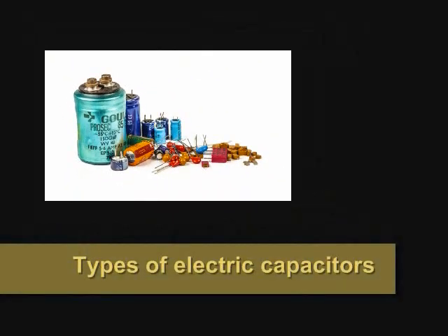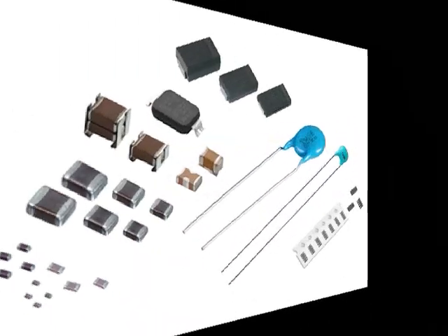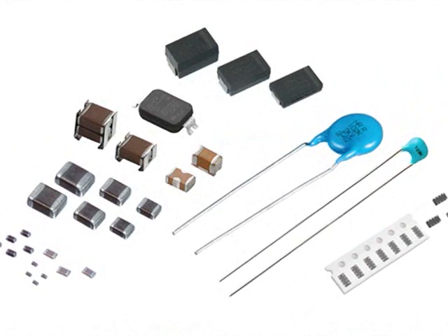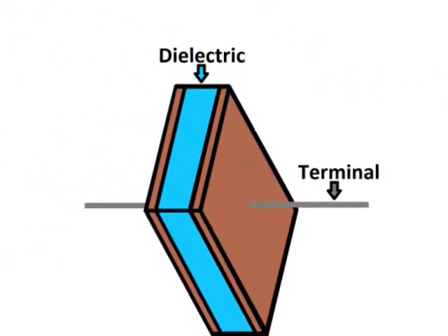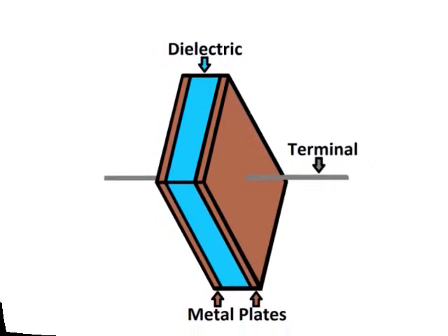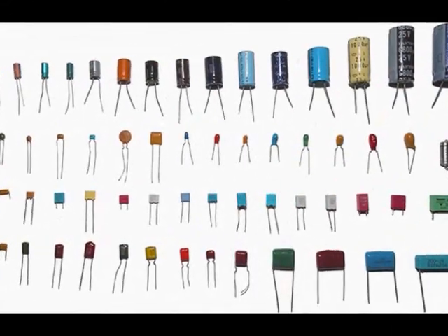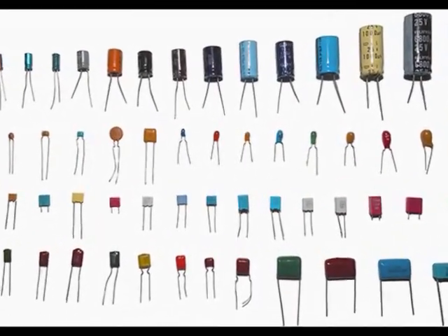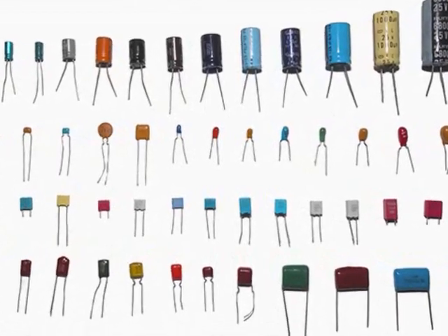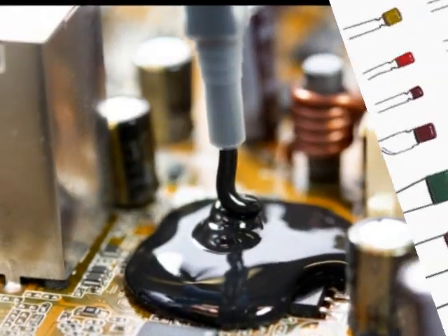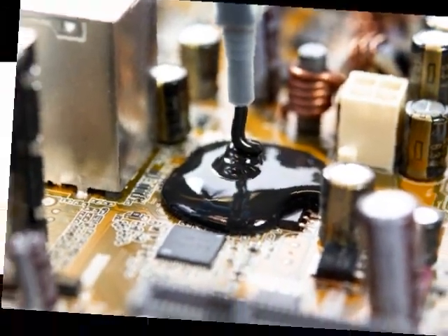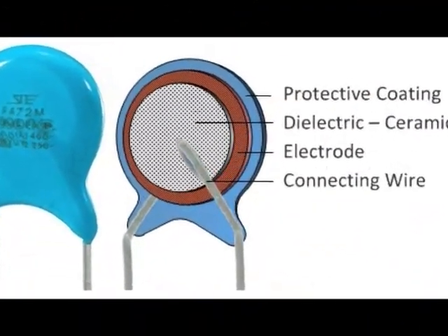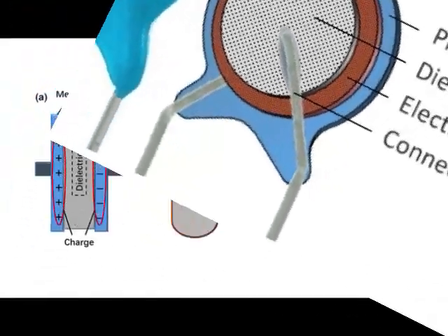Types of electric capacitors. Fixed capacitors are usually defined and identified by their dielectric. Dielectrics commonly used in fixed capacitors include ceramic, plastic, and mica. In electrolytic capacitors, aluminum and tantalum oxide are used as dielectrics. Tubular and entangled plates are types of designs of this type of capacitors.